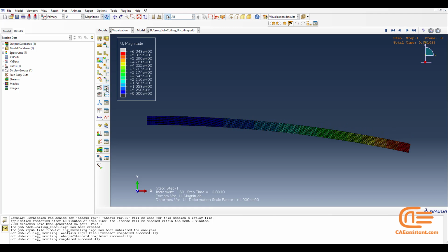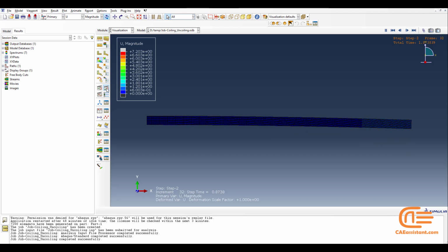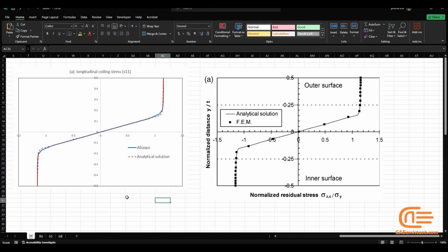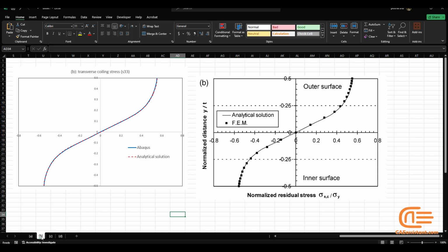These residual stresses originate from 2 main sources: 1, the coiling, uncoiling, flattening, and 2, the cold forming process itself. However, laboratory assessments of residual stresses across the plate thickness in cold-formed sections are challenging and sometimes impossible. Numerical cold-forming simulation addresses the limitations of cold-forming residual stress analysis. However, such simulations may present some challenges. We have discussed these challenges below.